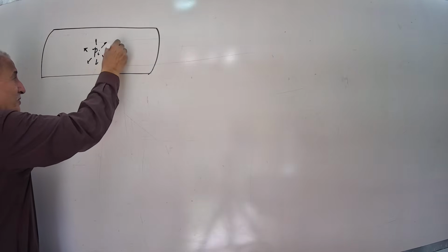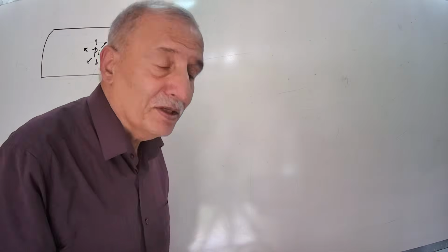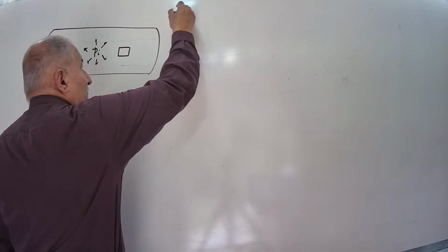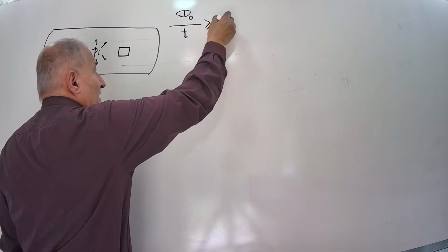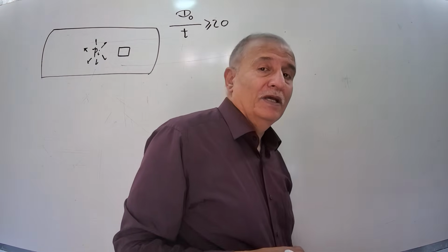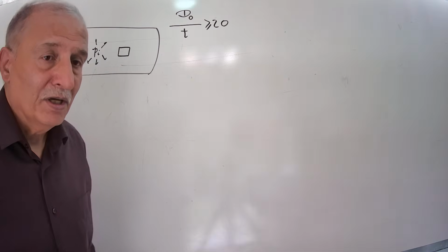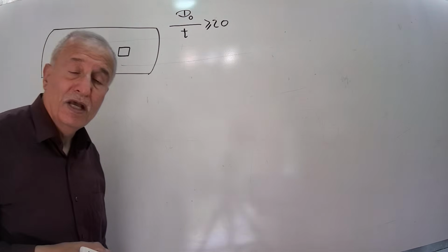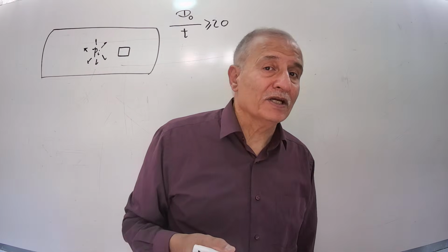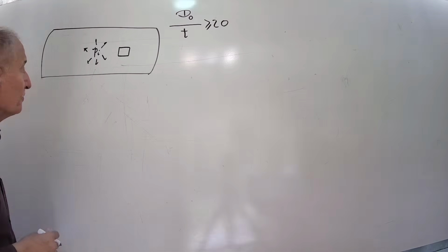the stresses that develop depend on the shell being thin. Thin shell means that the diameter divided by the thickness must be less than 20. This is the standard limit for considering a vessel as thin. Thick and thin vessels have completely different stress formulas and stress distributions.